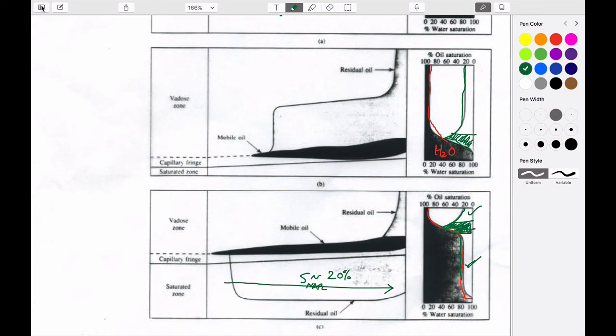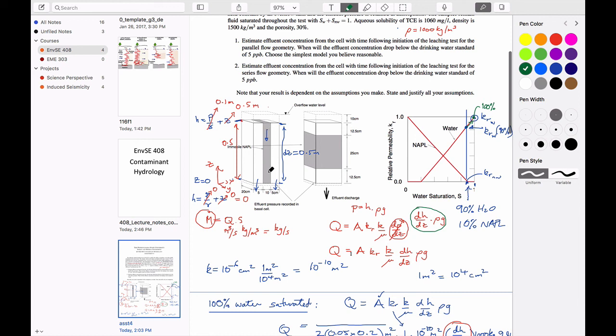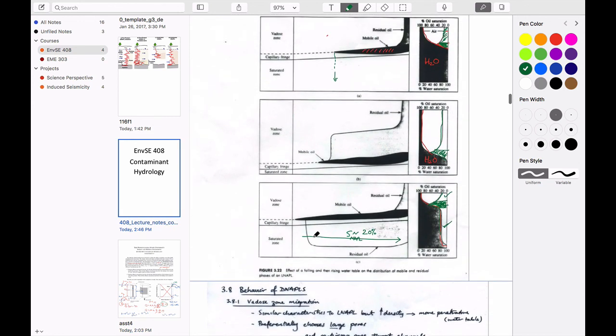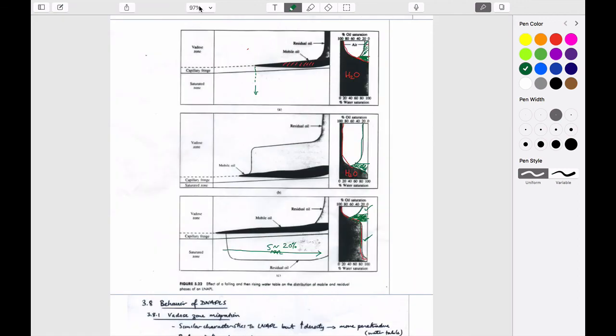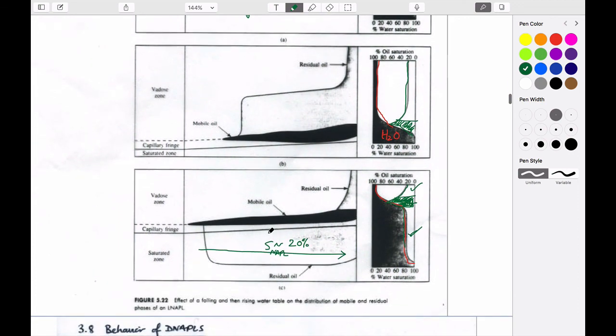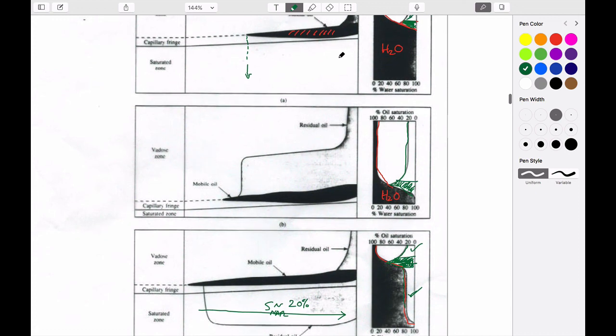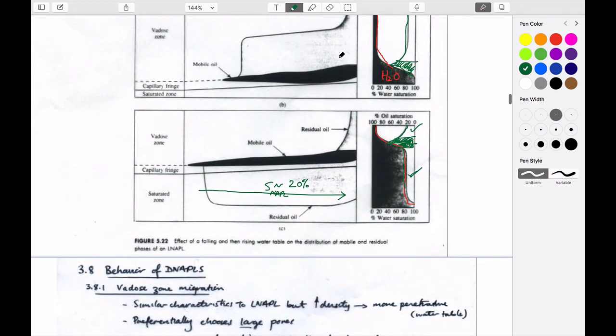And so actually, coming back to where we started off today, it's really not very different from this physical system, except that instead of things moving vertically, this is just switched on its side. It's traveling horizontally. We have a flow that's going along here. It's going to dissolve material out from here, transport it downstream, and take it to some compliance point, which is down there. And so having this rise and fall of the water table is, unfortunately, quite an efficient way of distributing this stuff below the water table, where it couldn't actually get before because of buoyancy. And it's just driven by the fact that between summer and winter you might have different elevations of the water table system. Okay.